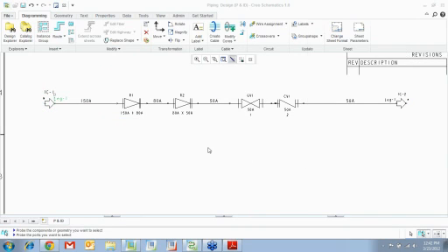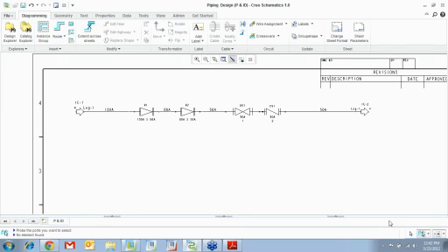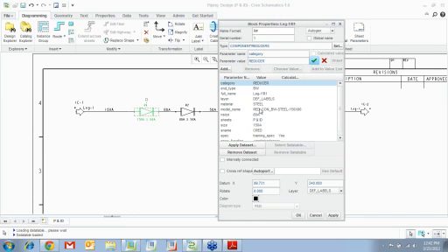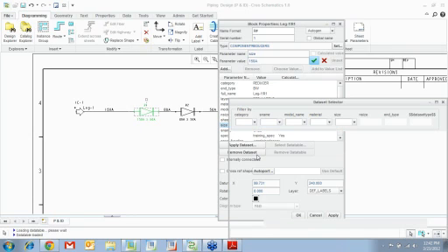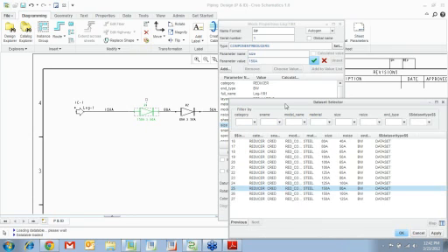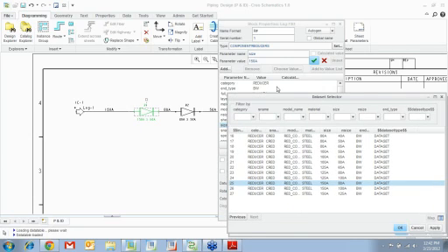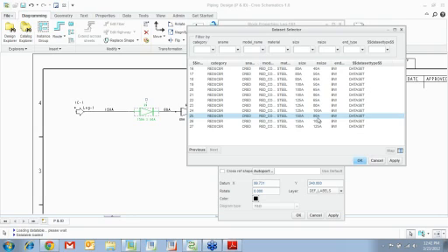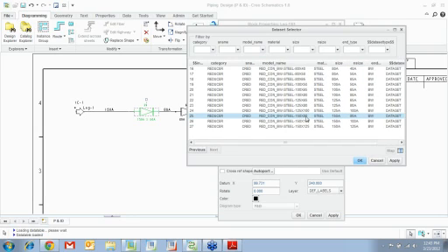Okay. Now similar to that, we also have valves. So I select that, go to the properties. You notice that you have all these properties, different sizes. So it's going from 80 to 150 to 80. You can apply a data set and you can see, hey, I want to go from 150 to 80. And notice it automatically picks the right size part.